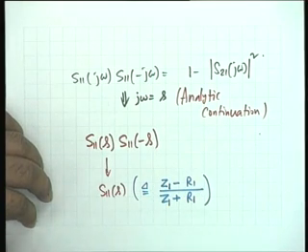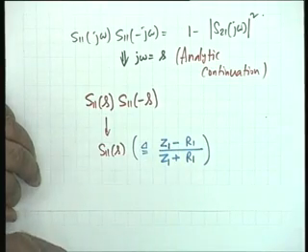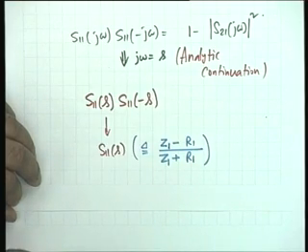Okay. Now, let me go slow. What is the property of input impedance Z1? Where should its poles be? Poles of an input impedance. It's a passive lossless network terminated in a resistance. Can it have poles in the right half plane? No, its poles must be on the left half plane.